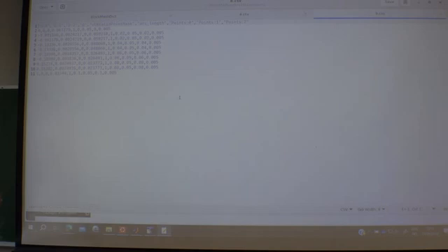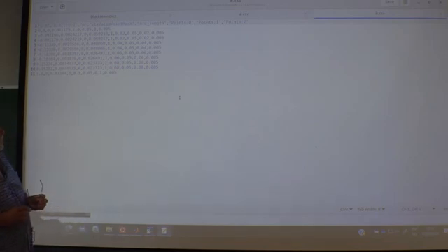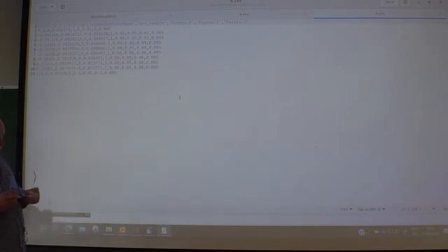So that one looks a little bit better, doesn't it? You have the velocities, U, V, W, you have the pressure, then you have something called VTK point mask, whatever that one is, and an arc length. Arc length, that is the distance accumulated from starting point to the end point. Whatever you need that one for, but at the end, X, Y, and Z. So this one looks actually reasonable.